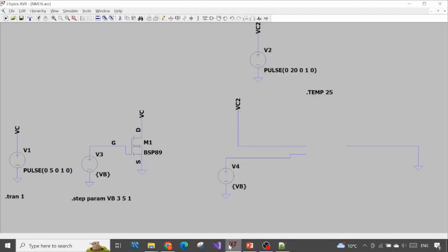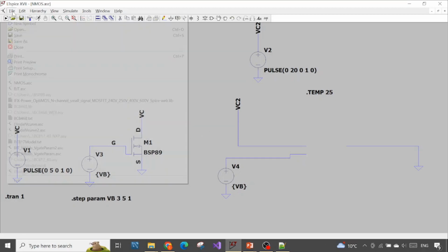ports. However, if you look at the device here, for a default symbol of a MOSFET, we have only the drain, the gate, and the source. Only 3 ports. 2 ports are missing. If the symbol doesn't match, in that case we have to draw by hand. However, LTSpice has a function to help us generate the symbol automatically. How can we do this?